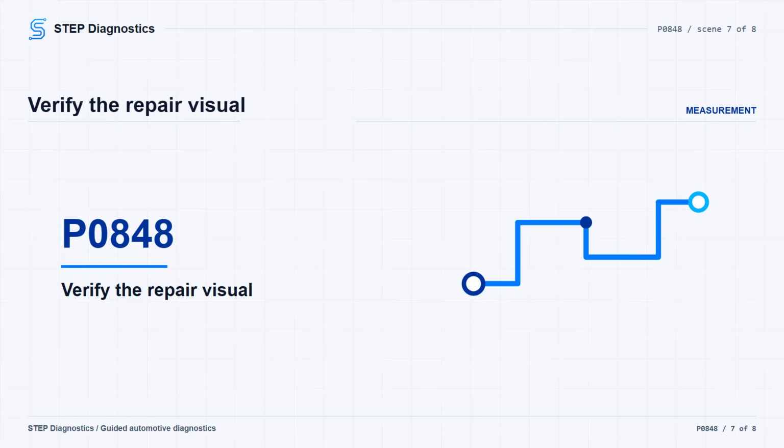Keep verification separate from the testing. Reconnect all connectors, turn the ignition switch to ON (II), and clear the code with the HDS. Start the engine and warm it to normal operating temperature when the radiator fan comes on. Test drive in third gear for at least 2 seconds, then drive in fourth gear for at least 2 seconds and monitor the OBD status for P0848.